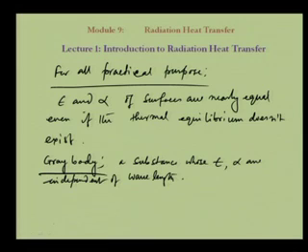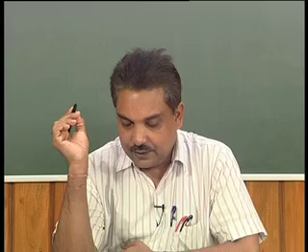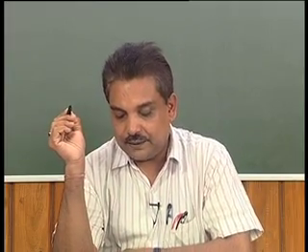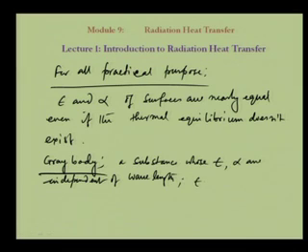We have seen that emissivity is not very sensitive to temperature and wavelength, and therefore epsilon and alpha can be taken to be the same even for surfaces not in thermal equilibrium. So, a gray body is also a kind of ideal body, with emissivity epsilon and absorptivity alpha less than 1, whereas the black body, the ideal body, has epsilon and alpha equal to 1.